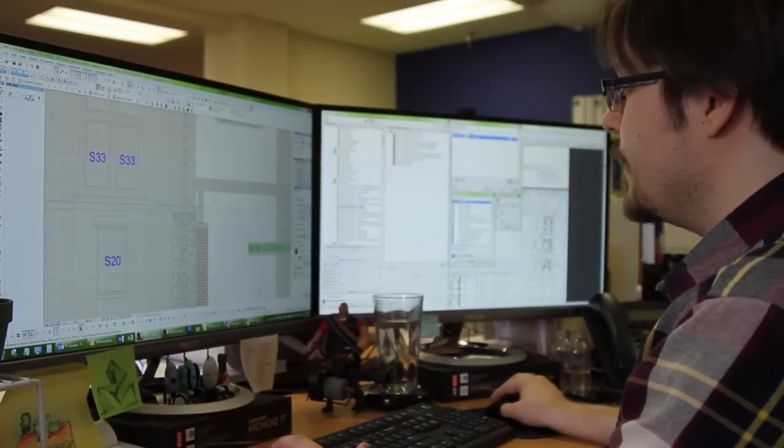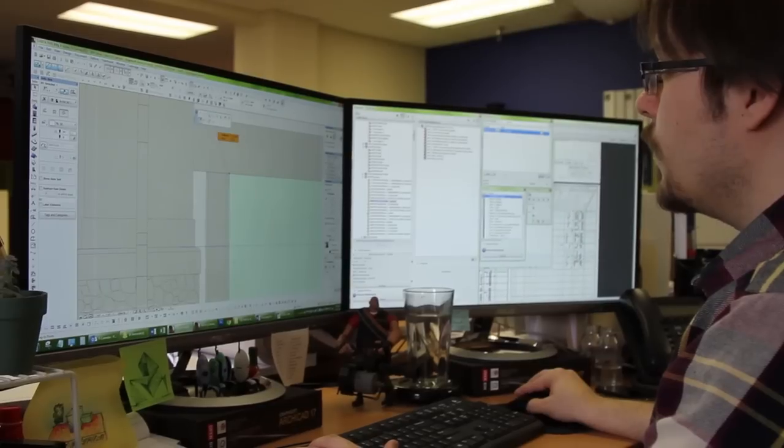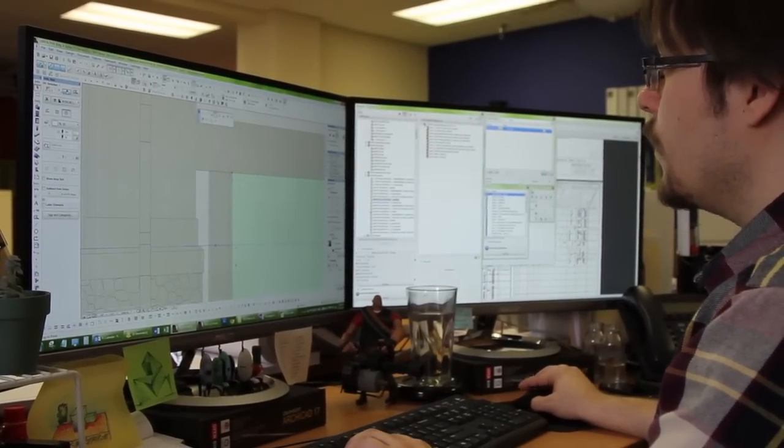Because we're not doing a whole lot of organic stuff, I don't need a bigger package to do 3D modeling with. But usually for the exterior shots, I'll start with what we have modeled in ArchiCAD and export that to SketchUp, where I might do some finer details, add those light fixtures, add the park bench, and get the scene set up